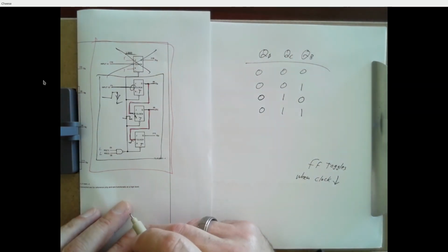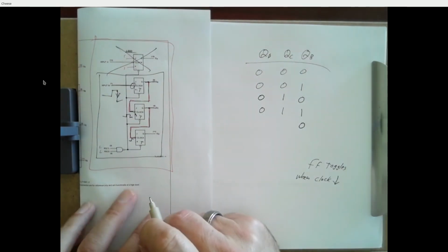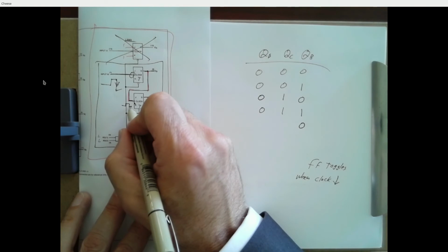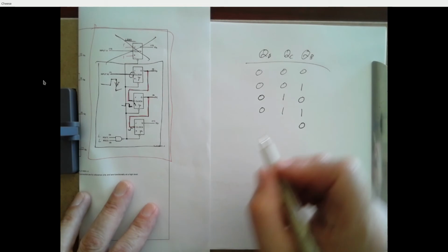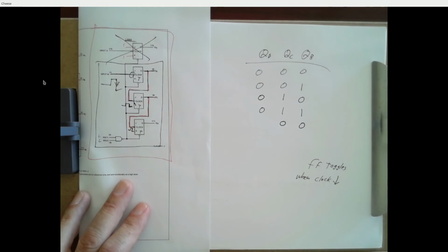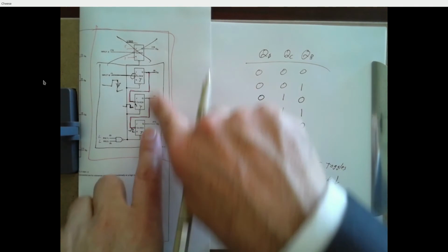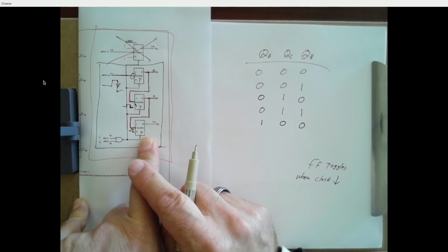But one more time, and this is where the good stuff happens. Input B drops. We know QB is going to toggle. What's that going to do when QB goes from a 1 to a 0? Drop C to 0. Changes QC to a 0. What does that do when QC changes to a 0? Yeah, that toggles QD, so now QD becomes a 1. So this is how your counter was counting. It was really 3 toggle flip-flops with each output feeding the clock of the next flip-flop.